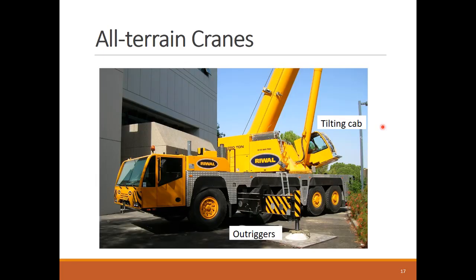All-terrain cranes come with a high price tag compared to truck cranes due to their combined benefits of mobility on and off roads. They are best used in job sites with multiple lifting locations with no need for graded sites. They are incapable of pick and lift operations where they can lift a load and move with it in the air for a short distance. The only other crane capable of this pick and lift operation is a crawler crane.